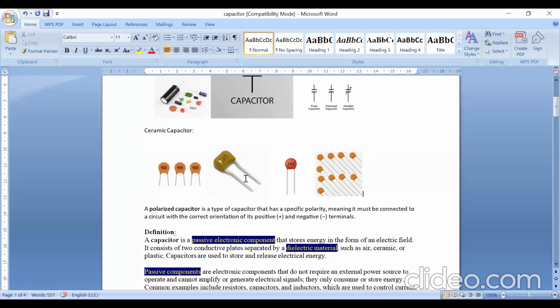These are all ceramic capacitors. You can read the value from most ceramic capacitors. See, look here: 102, 104, 103, 105, 101. So you can read the value from most capacitors. The only difficulty in reading is with the very small ones. In the last picture, the capacitors are very small because there is not much space on them to put the value. Here they can't write the value.